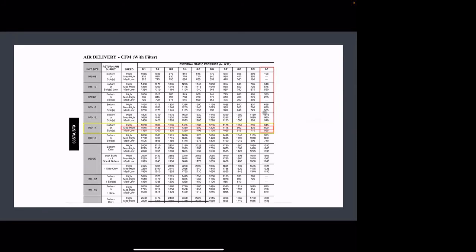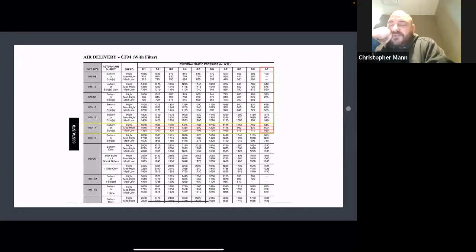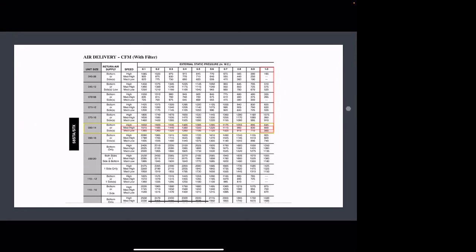Then you lower the gas pressure. And what happens when we lower the gas pressure? Not getting enough BTUs. We don't get enough heating capacity. We're trying to match the CFM versus actually correcting the issue. What else happens to that heat exchanger? Soot can happen. Yep. Has anybody ran a combustion analysis on a system that we've lowered the gas pressure outside of manufacturer specifications because of the scenario here?